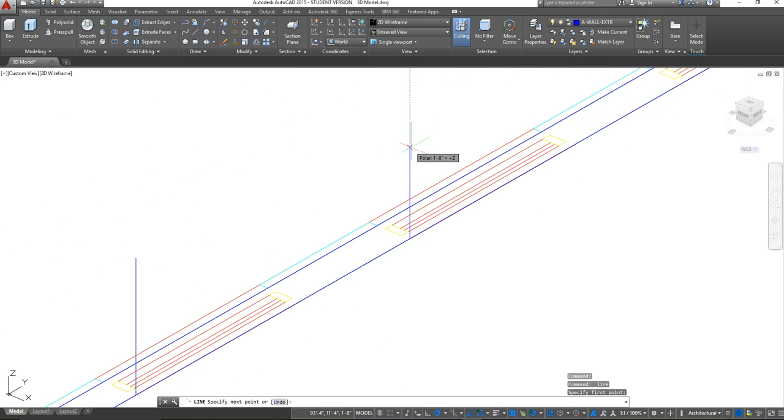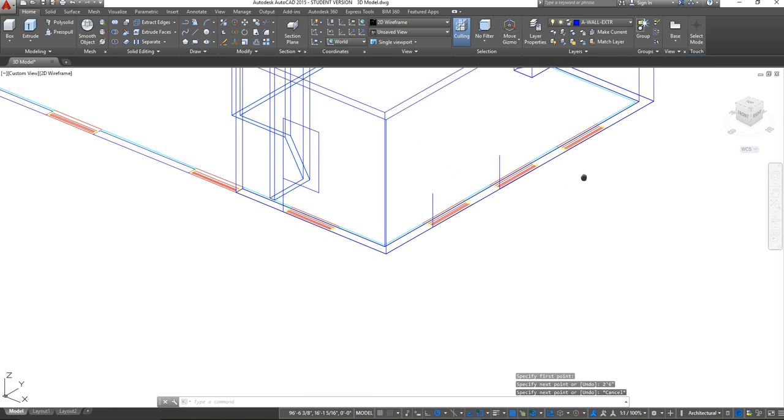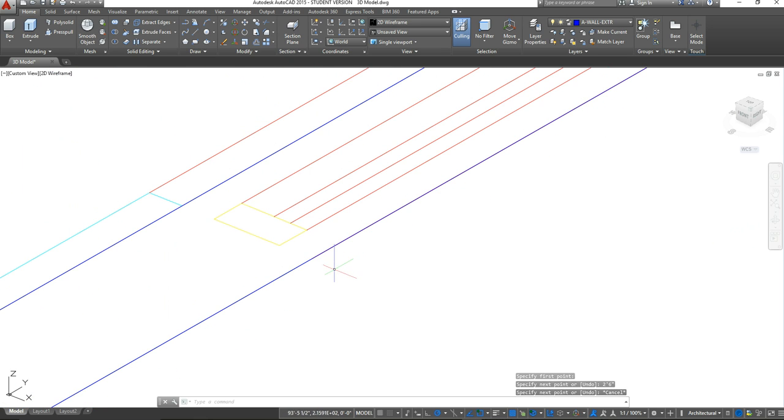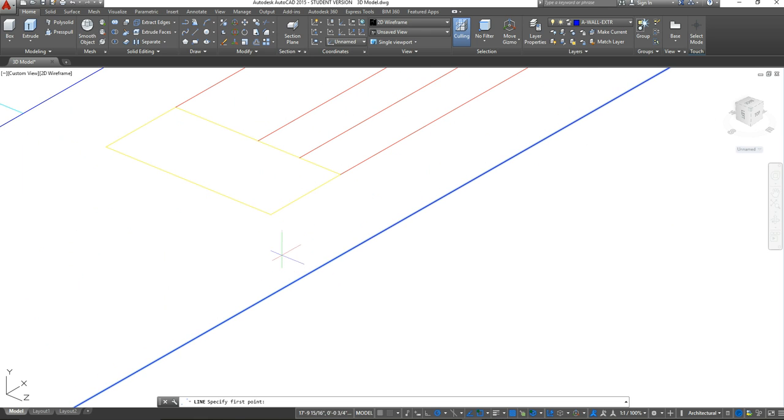And I just want to take that up again, that 2 feet 6 inches. Press escape. Now I got one more window to do. So again, I'm going to get that line tool. And it actually may be snapping on those points for you. So if it's doing that, it should line up. So right now, when I hovered, it created that endpoint, and then I see that green dotted line, and it actually lines up with the edge that I'm trying to select. So that means I'm good.